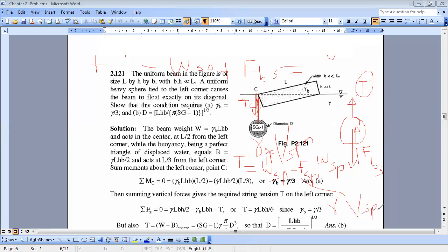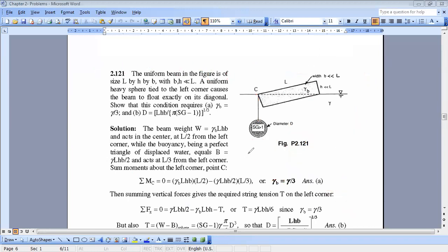So let us take the volume of the sphere into factor. What do we get? We get then that the tension T is equal to the volume of the sphere times the weight, times gamma of the body, okay, of the sphere, if you want, we'll call it now gamma of the sphere, minus gamma of the fluid.